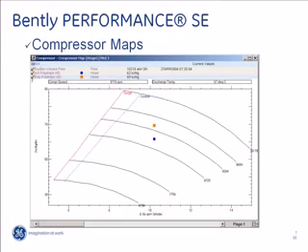For process compressors, our Bentley Performance solution provides compressor maps to the user where we display the actual calculation results versus the manufacturer's expected results at design conditions. By displaying all this data on a single display screen, the users are able to compare the actual performance with the expected performance, thereby able to discern any performance degradation at that particular moment in time.